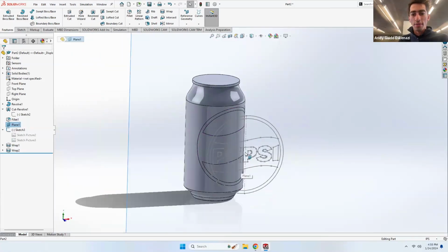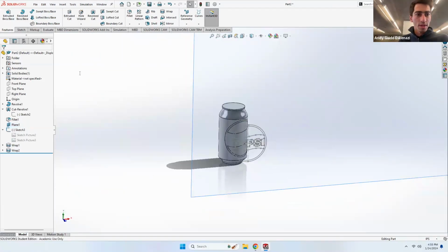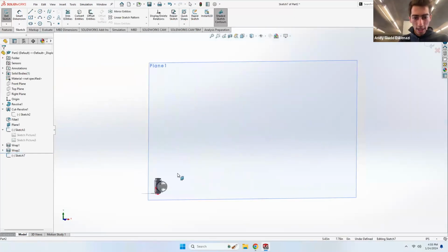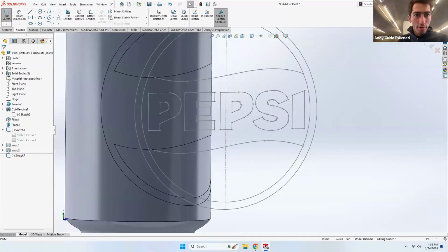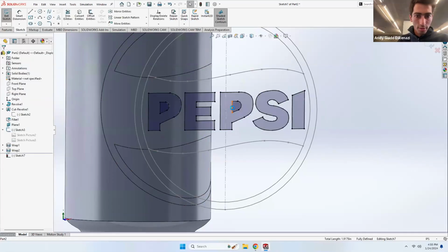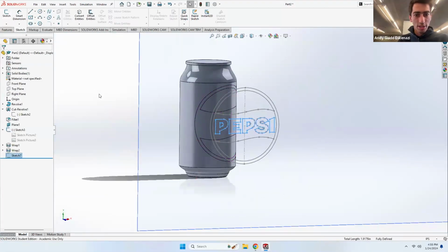So now let's finish with the word Pepsi. I'm going to click on sketch. I'm going to do a sketch on plane one again, and I'm going to convert entities. I'm going to select chain, and I want to do all of these guys. Very good. And I'm going to exit my sketch.